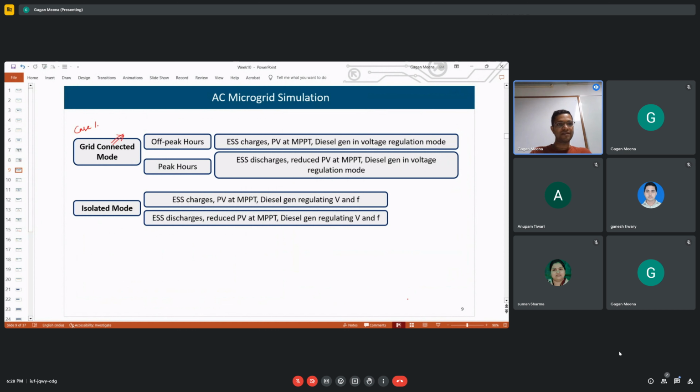If the voltage is more than 0.9, it will enter the steady state, and the Q requirement at that time will be less than 40%. If the system is already operating in state 1 and the voltage is still more than 0.9, but the Q requirement is more than 40%, then it comes to the dynamic state.